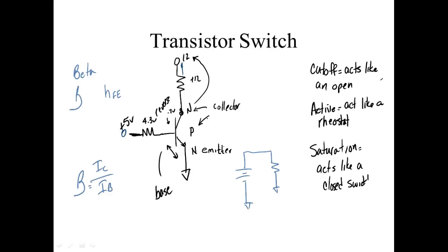So this is why it's pretty dangerous to run your power amps unloaded, by the way. You can blow them suckers up because you've lost the resistor, and you get what we call reflective power. So if you've got a 100-watt amplifier and you unload it, the 100 watts is going to be reflected back into the amp, and it'll blow what we call your outputs. So if you've got a big power amp in your car and it kicks off one time because of an overload, don't keep resetting it, because you'll blow the outputs on your $500–600 power amp. It might even burn your speakers up because it's putting DC on them instead of AC.